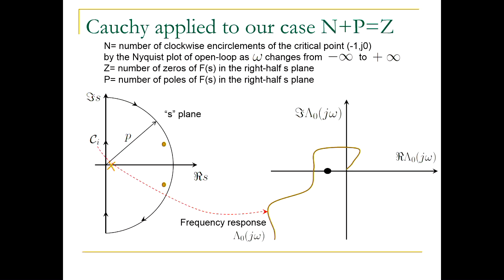By the way, you may say, well, why is this reasonable? Well, if I know my plant transfer function, typically you can assume you know whether the plant is stable or unstable. You would know your controller. But 1 plus controller times plant would give you a totally different thing, which is presumably harder to figure out, what the closed loop poles are.